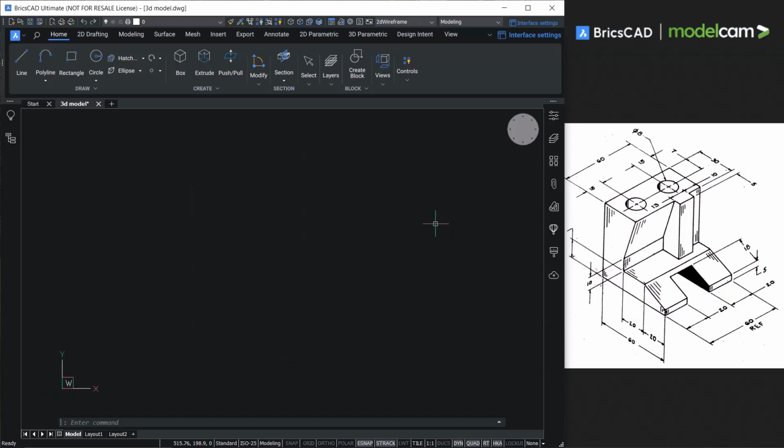Let's change the view to top front left to match with the view of the model in the drawing. Click on top front left face in the Look From widget. To start with, let's create this particular profile. You can see that this is a left face.